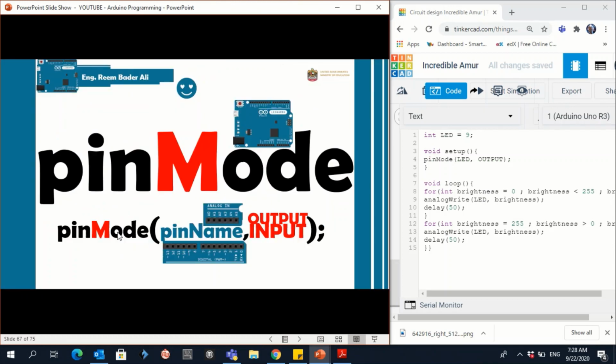the pin mode function, then the pin name, which we wrote and declared here, so we will put it the same, LED, then comma, then it is OUTPUT, so we write it here. Don't forget that OUTPUT and INPUT here are both in capital letters. All of the letters are capital since it's in red here. And in pinMode, everything is small letter except the M.